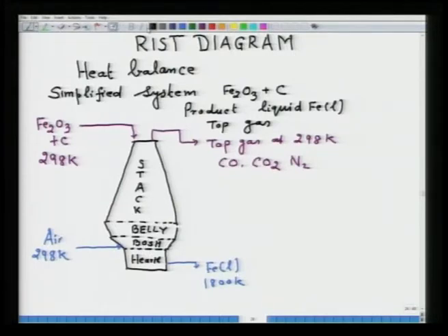That means we are attempting to understand how the heat balance can be transformed into an equation, and we will develop the equation such that inputs, for example the gangue in the iron ore, can be simply added to it. Slag at the output can be simply added to it, and so on.